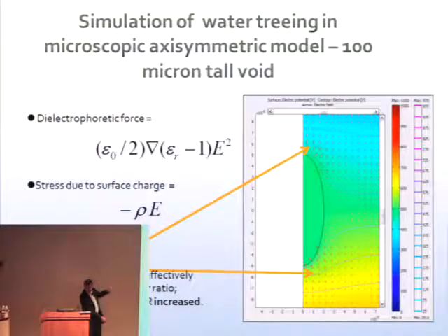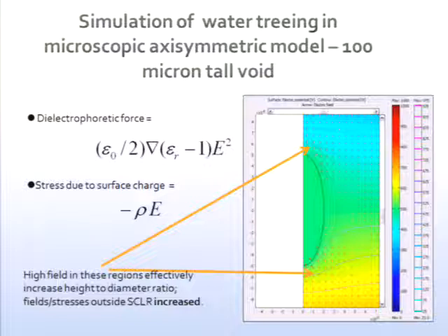I would look at it very differently, because you can look at it quantitatively. Basically, what you're going to have is a space charge limited field there. You can calculate the space charge density, which may be a couple of thousand coulombs per cubic meter. You know what the field is because that's the space charge limited field, and therefore you have a cyclic force density, which is the field times that charge density. Yeah. So you can make that quantitative fairly accurately. I agree. This only occurred to me about 4 o'clock this morning, so I decided I'd throw it in and see how we went.